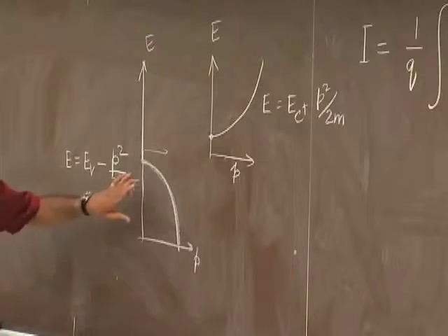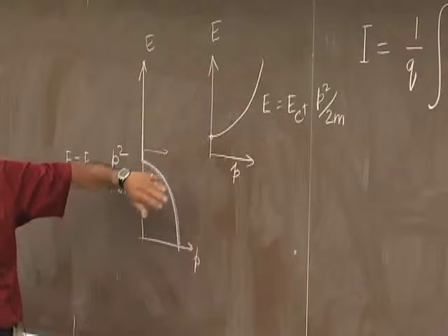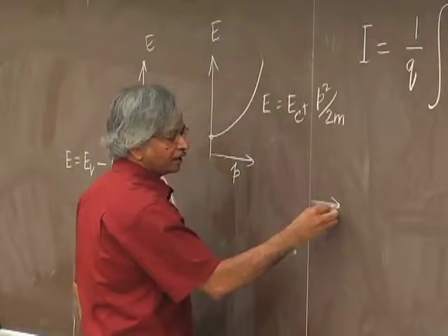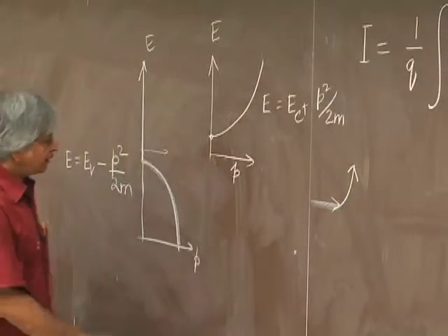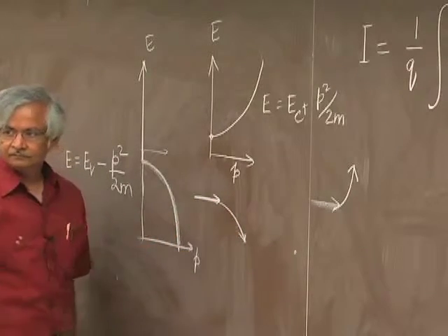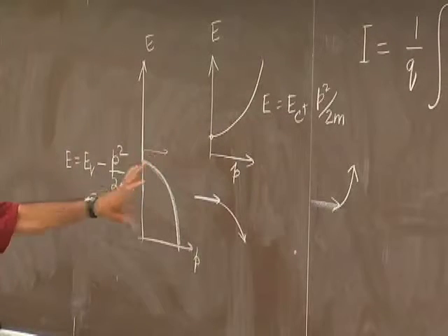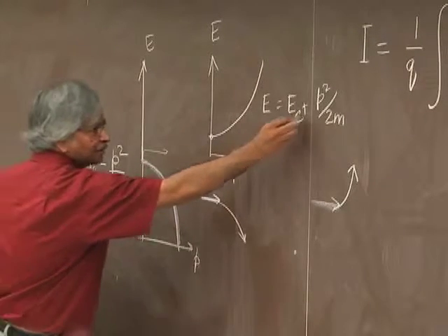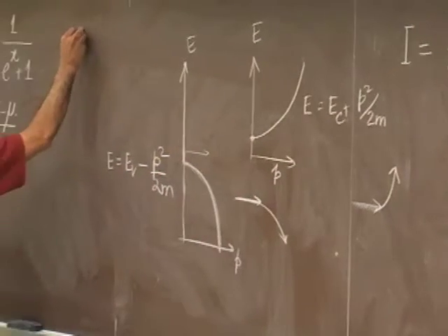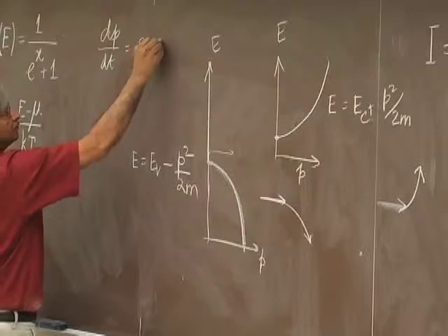And the difference between N-type and P-type comes about because when it looks like this and you put in a magnetic field, let's say an electron going this way curves upwards. In a material like this, an electron going this way will actually curve downwards. So it's not an F1 minus F2 issue, it's a different thing. And that is, again, only because of this plus and this minus sign here. Because, as I mentioned before, the way you think about it is dP/dt equals Q V cross B.